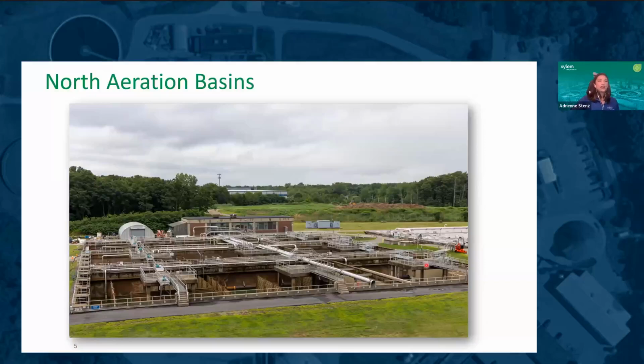Both the north and south aeration trains at Brockton are 4-stage Bardenpho processes, making use of a pre-anoxic, aerobic, post-anoxic, and post-aerobic zone to optimize total nitrogen removal. These north trains are run on ammonia-based aeration control via an ammonia sensor, which sits right here in the aerobic zone.